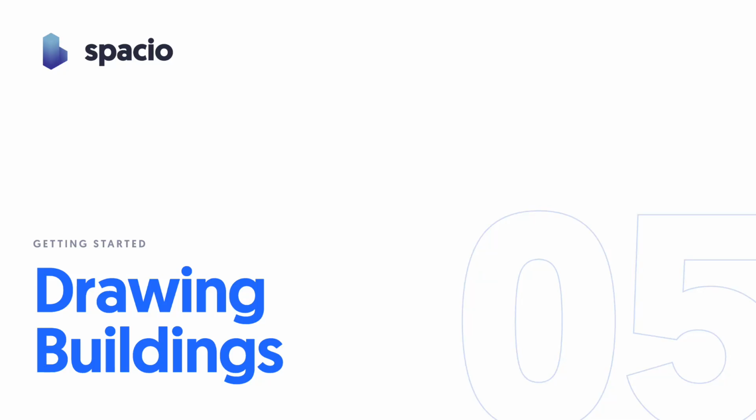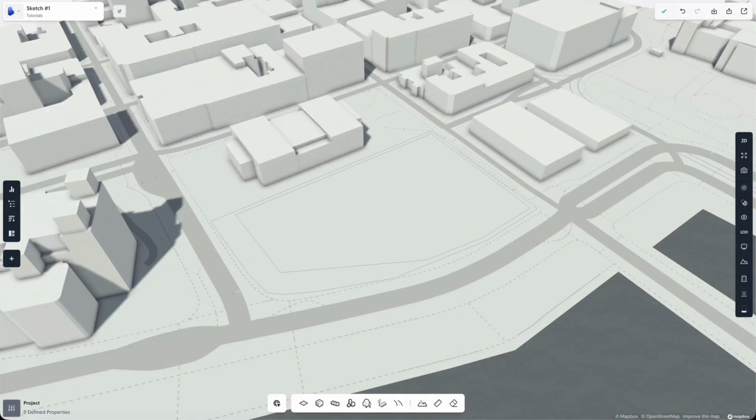Right, welcome back. Last tutorial we drew the plot. Now we put a building inside it. Grab the building tool from the bottom toolbar and you've got three modes to draw with: rectangle, freeform and centerline. Rectangle and freeform behave the same way under the hood. Pick whichever fits the footprint you're drawing.